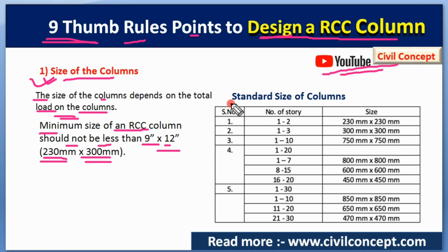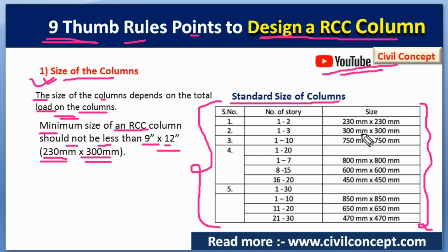Here you can see this is the standard data. It has come from the tab. It is not necessary to provide the column size like this, because it depends on different factors like seismic load, soil condition, etc. If we are constructing a building up to 2 storeys, then we can provide the standard column size of 230 mm by 230 mm.